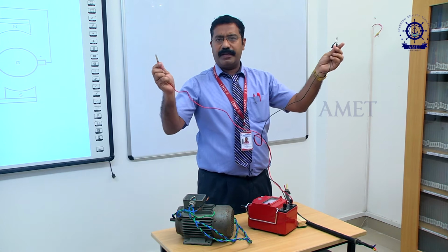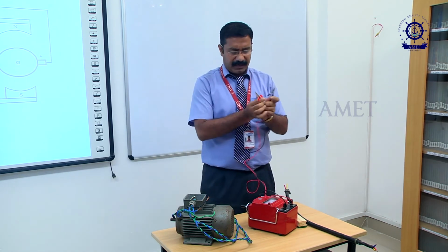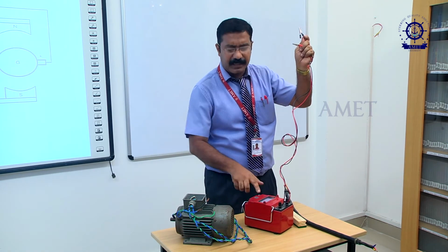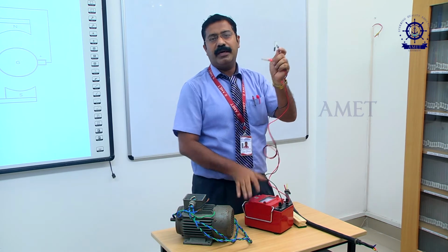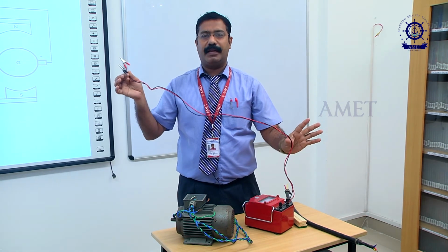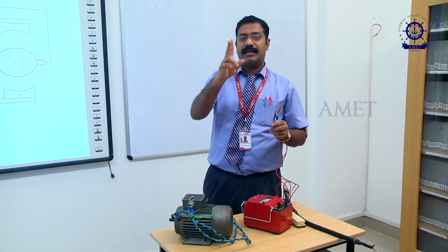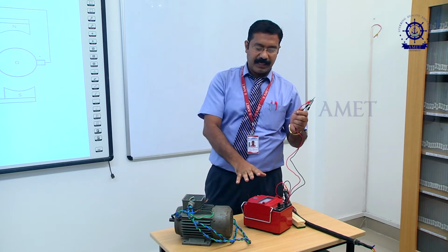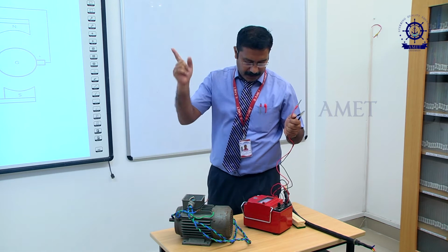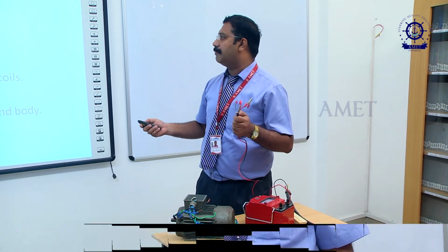Now I am going to open it. Open circuit means resistance is infinite. See, if I crank the shaft, the resistance being shown is infinite. Therefore I can easily tell that yes, my instrument is working properly. This instrument is a combination of two instruments: one is an ohm meter, the second one is a DC generator. We'll go on to the next slide to know what can be done.